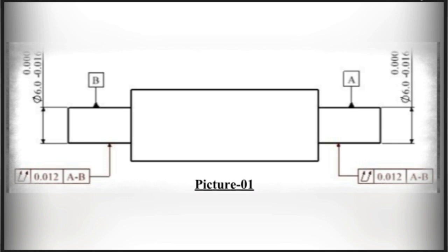First of all, we check the angle of the V-block. Depending on the form deviation of the datum feature, the angle in the V-block can affect the position of the datum, which also affects the measured value.